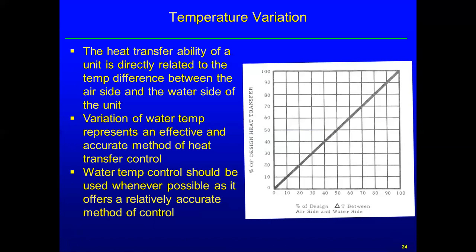The big variation would be if you have changing amounts of ventilation air. But if the occupancy is pretty stable, then you would expect the quantity of ventilation air to be roughly the same, and so the entering air temperature to be relatively the same. That could set up a very stable operating situation.